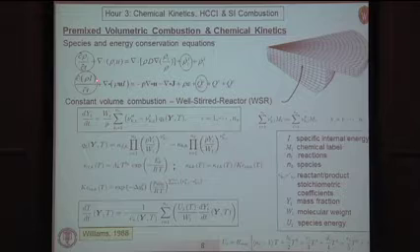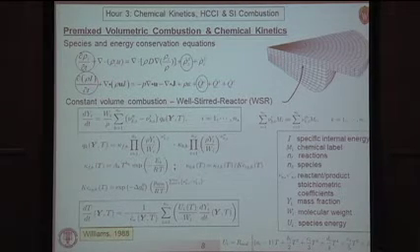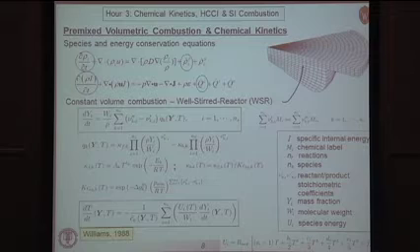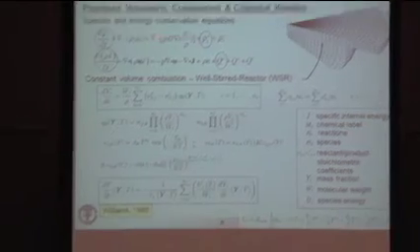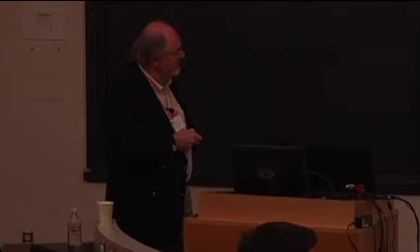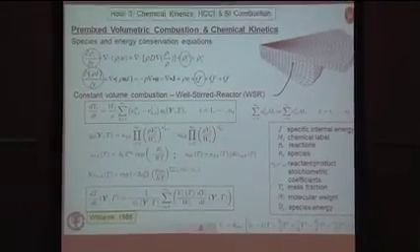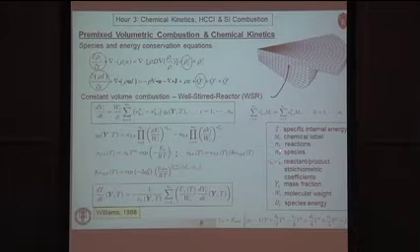Along with them are these equations governing energy conservation that we spoke about before. Again, I just have the time term and the combustion term. Don't have to worry about any of the other gradient-driven terms. So this equation then looks like this. You've seen this already, I'm sure, in many of your combustion classes. Basically, we have an equation for the rate of change of species mass fraction for the NS species. That's driven by this term QK here, which is the difference between forward and backward rates once we specify a system of reactions. In this case, we have NR reactions.